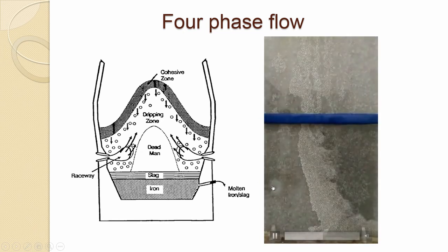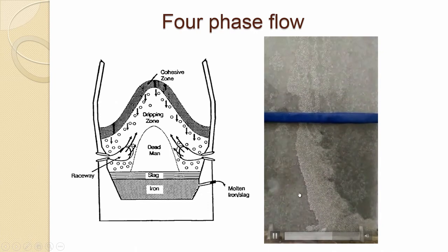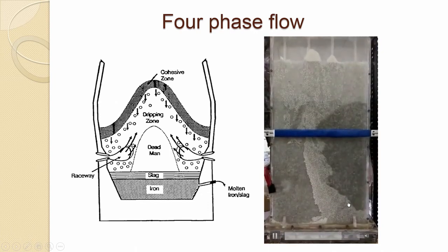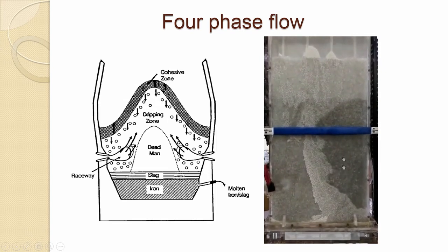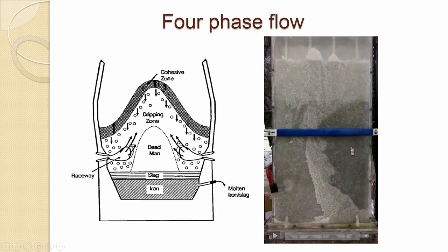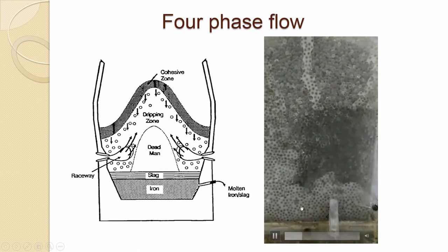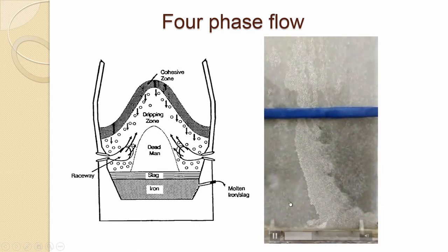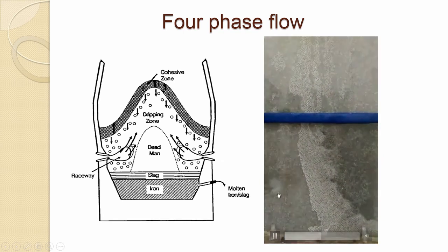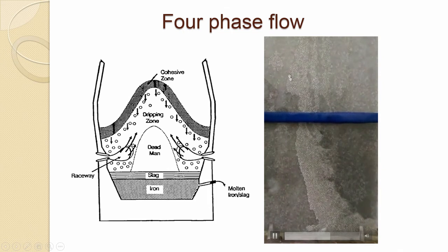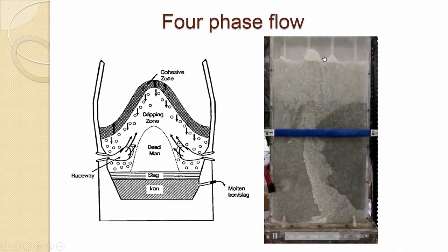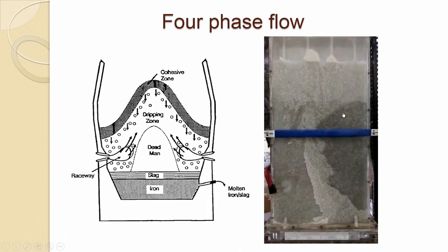Gas is coming from this side, and fines are coming from the top. Fines are deposited, blocking the pores and forcing liquid to build up, and then the flooding and bubbling has started. It is a classical example which we talked about before, about the flooding and loading things. So, you can see in this one how the loading and flooding is occurring. In this case, the solid movement is not there, it is stationary. So, this is resembling the lower part of the blast furnace, and deposition of the fines one can see even at the top, but liquid accumulation is notable.